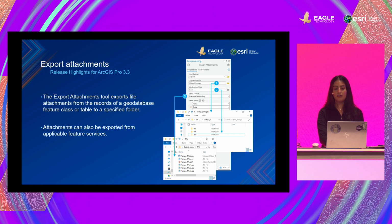So you have the option to have your attachments grouped together into subdirectories using a subdirectory field, so you can organize them based on field values. It honors selected features in an active map or selected rows in a table, so make sure you double check your selection before you run this tool. And the exported attachment files will be the same file type as when added to the geodatabase. So if you have a PDF file, the exported file will be a PDF as well. So this new tool will be a time saver for managing and sharing attachments.